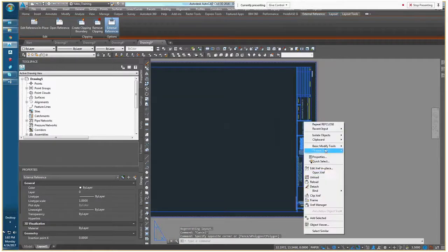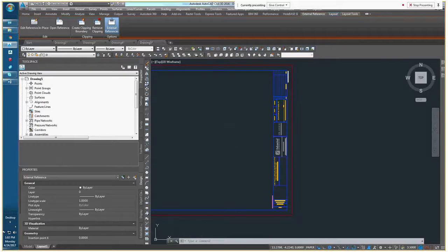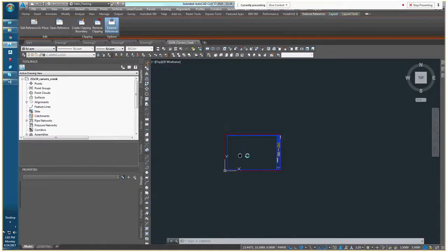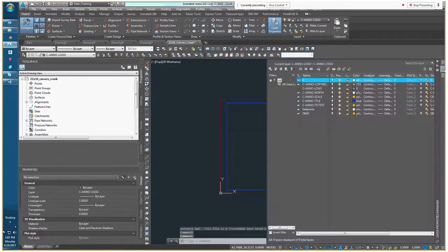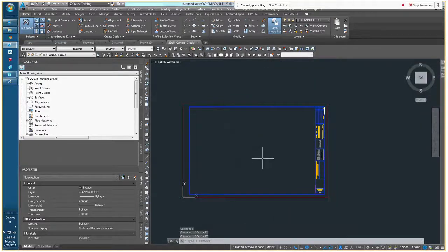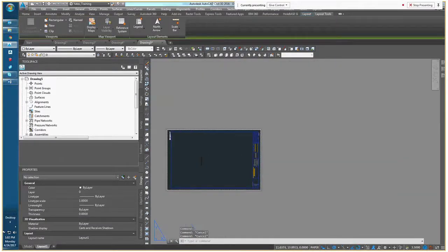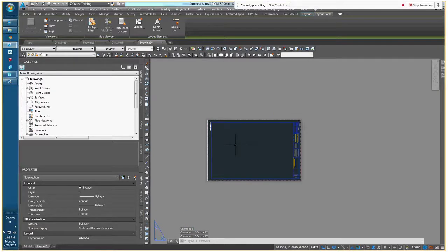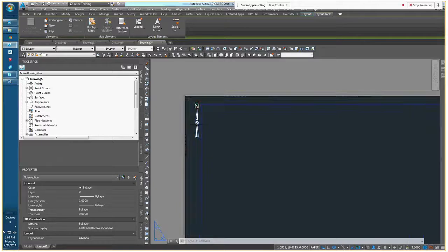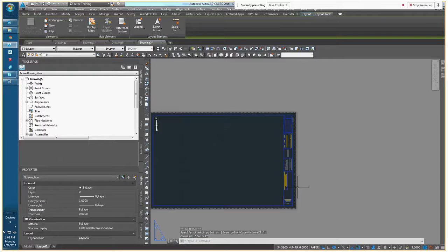And what you'll find here, when I go to Open XREF by the right-click menu, we'll see that this object is actually in model space of, it should be a detailed DWG template. You can tell that by its layers list here. Okay? So, I'm going to close that without saving. So this gets us into a discussion about model space versus paper space and where we can talk about scales and a little bit about XREFs and some other things going on. So within the Civil 3D template, I would just move this north arrow into the title block a little bit better.